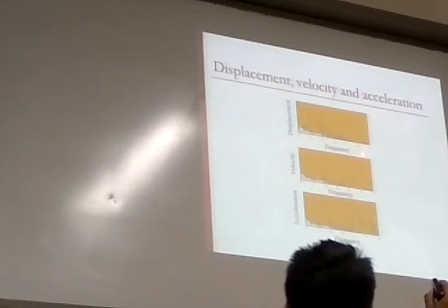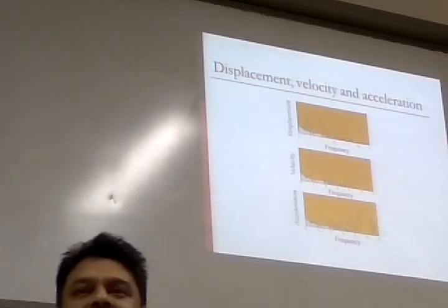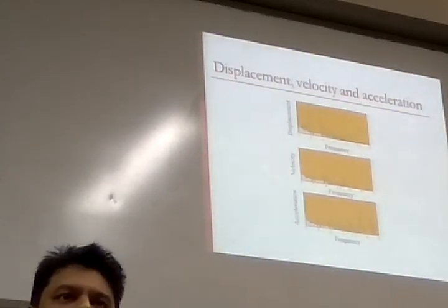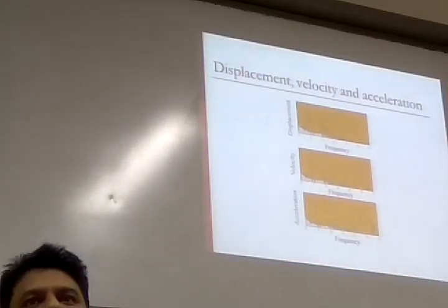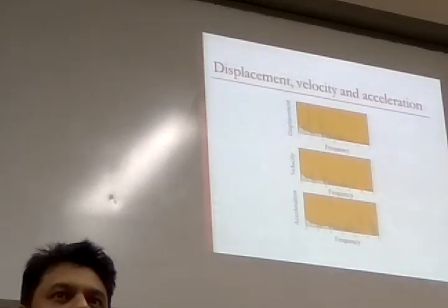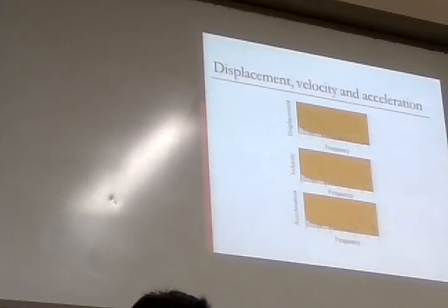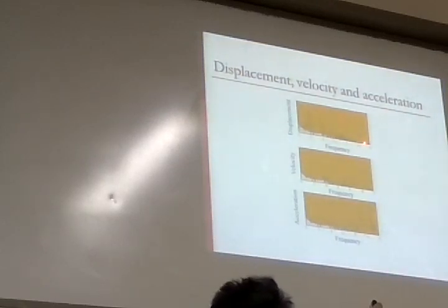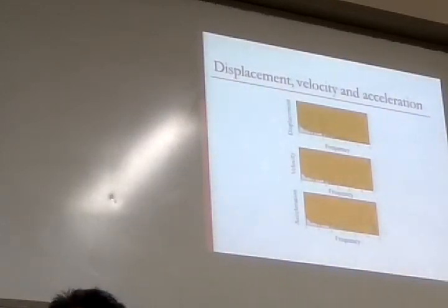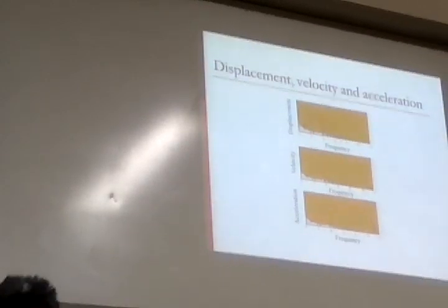For instance, let's say these signals correspond to some fault in the rotating fan. So when I am doing fault diagnosis, I am interested in knowing whether my fan is good or it has developed some fault in it. Basically, I want to know the magnitude of this, whether it has grown big. If there is no peak at all, it is actually small and ignorable, then I have a threshold. Up to that, the fan is in good condition. If it starts becoming a peak, then it has developed some fault. That is what I wanted to see.